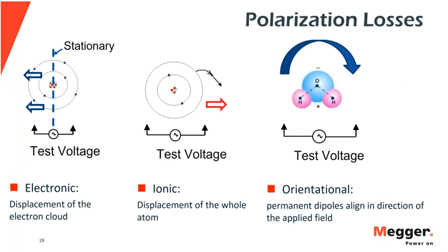The first group of the 3 polarization processes are due to fixed charges within the material. So just to give you an example of how this is working and how polarization processes contribute to losses measured in insulation, let's consider the electronic polarization. This is the fastest occurring of the processes, happening immediately upon application of the field, and we're talking probably in the microwave frequencies.